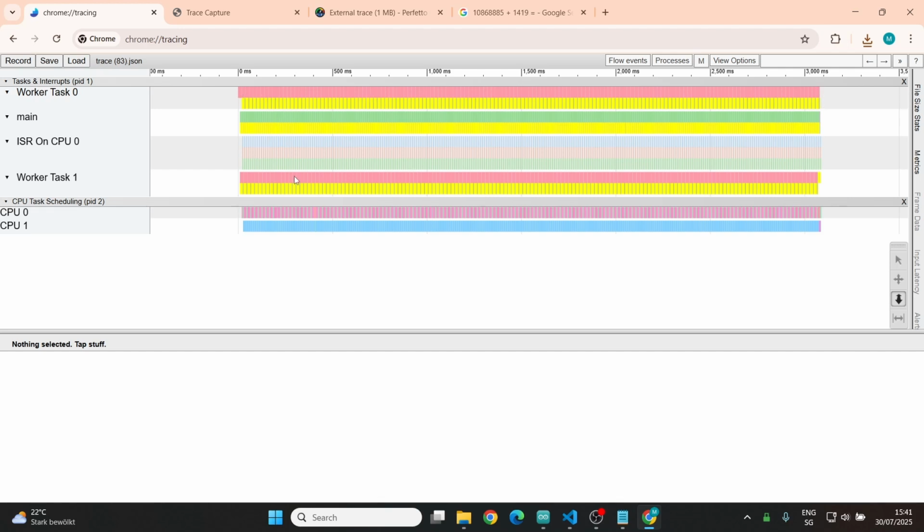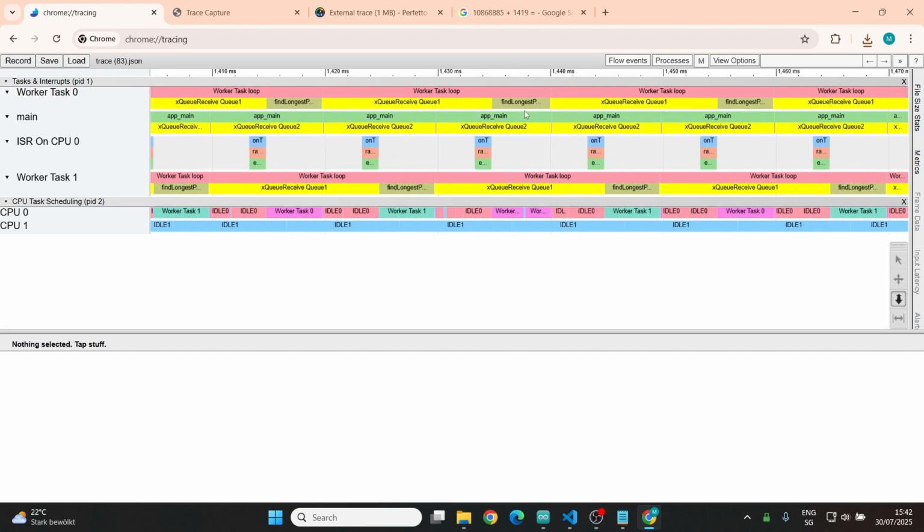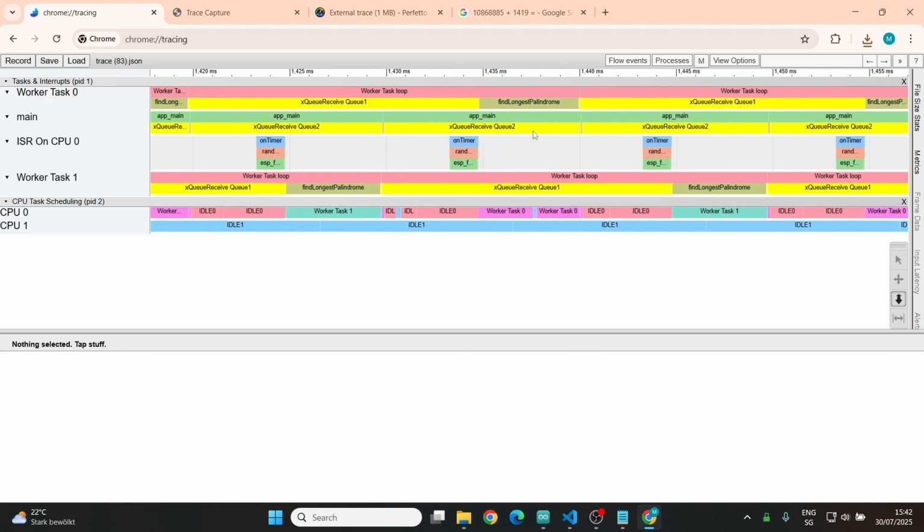The length depends on how many tracing macros you insert, because mabutrace is continuously saving these timestamps into a ring buffer, and that ring buffer by default is 64 kilobytes. So the more tracing statements you take, the shorter the entire duration that it captures will become. So keep that in mind when you insert tracing macros. But that's now what I get.